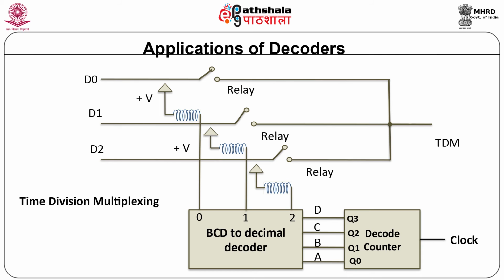Multiplexer by default should accept data from many sources and send it over transmission line to single destination. In this case, output is generated in a time multiplex manner, that is, one at a time, depending on the decoder input coming from a counter.